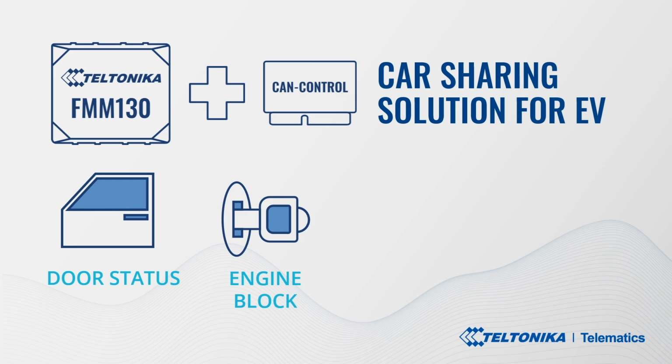You can cut the wire of the ignition button and place a relay through it. The relay opens or closes the connection to ignition. The second way is to cut a brake pedal signal wire and place a relay through it. First, you need to push the brake and turn the ignition on, and you will start the engine.